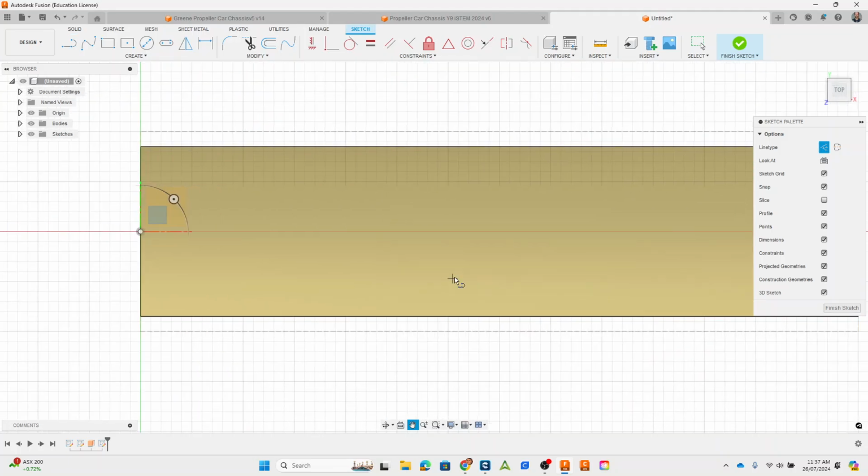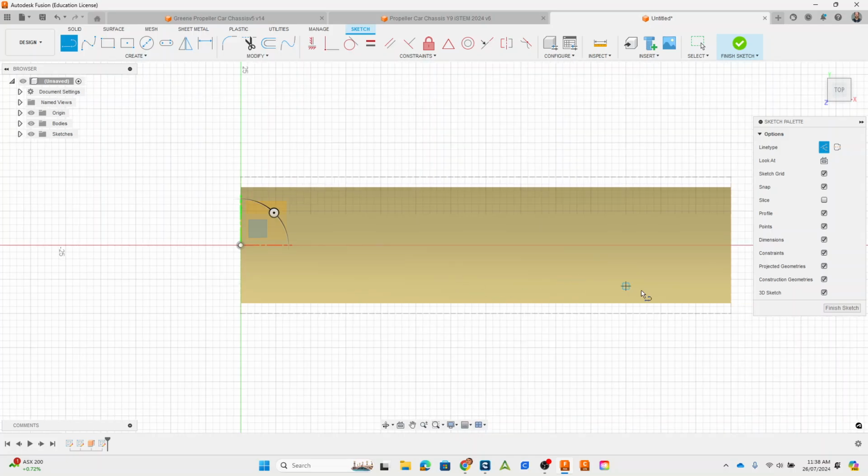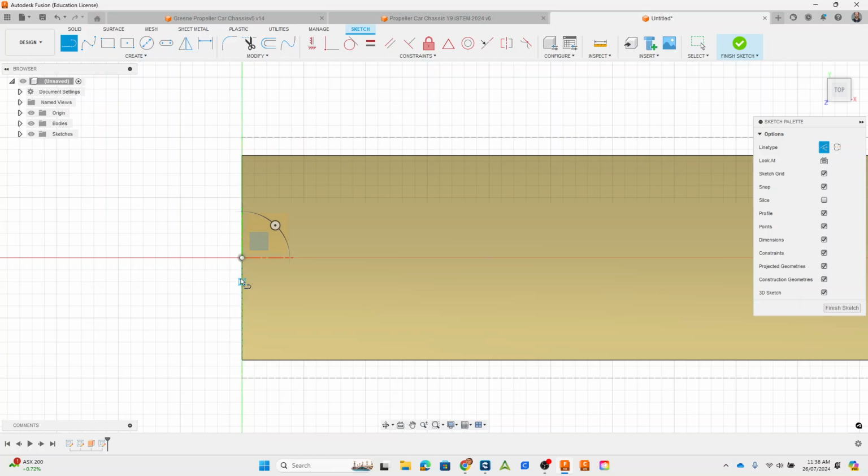and some critical parts of your design that you can get wrong at this point. You want a small little node connecting all of your propeller blades together, okay? So you want to make this initial sketch here, there's a line that goes here. You want to make that fairly small, okay? And I'll show you what I mean in a second. So I'm going to make this go up about 3 millimeters. So I'm going to type in the number 3. I'm going to go OK.